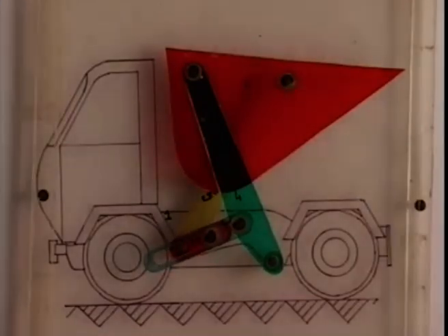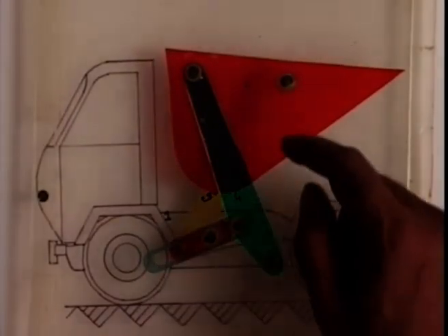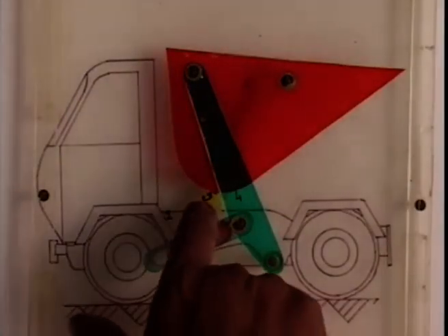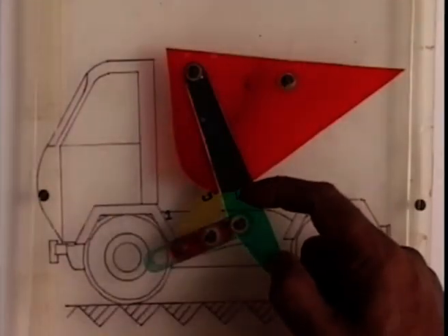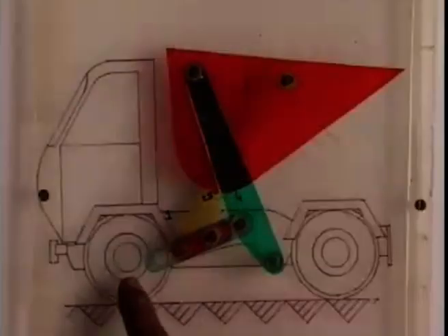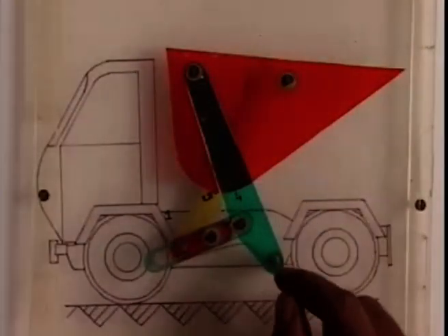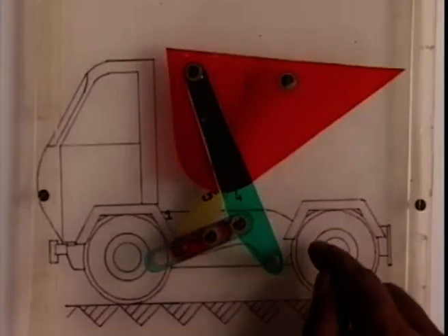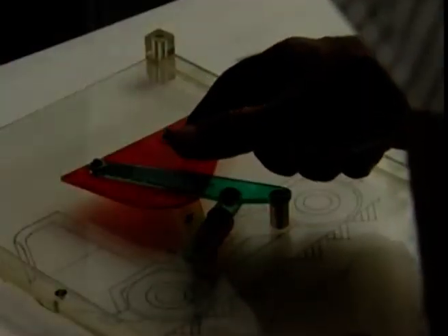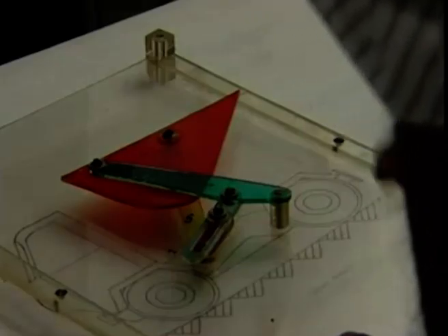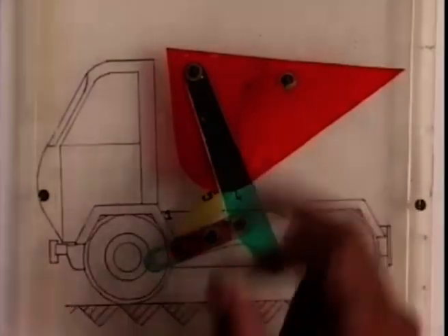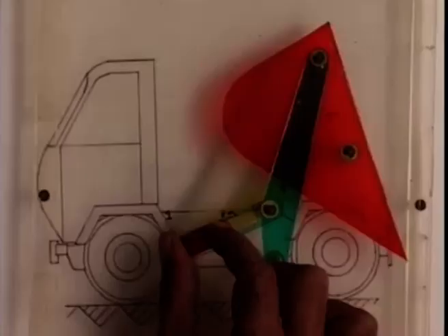Let us now look at the model of this tipper dumper. Here, the dumping bin is the coupler of a 4R linkage consisting of this yellow link and this green link. This yellow link is connected to the fixed hinge mounted on the body of the truck. Similarly, this green link is connected to the fixed hinge which is mounted on the body of the truck. So, of this 4R linkage, this dumping bin becomes the coupler. Our objective is to make this dumping bin move in a prescribed manner from this transport configuration to this dumping configuration.